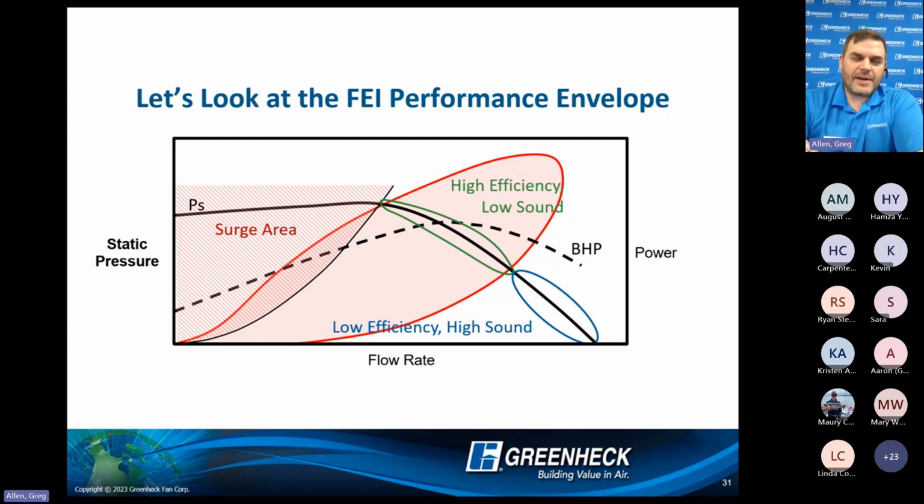Now, let's stretch just a little bit further. When you do employ technologies that give you variable speed, whether it's a VFD, an EC motor, or even a belt drive fan where I could adjust sheaves and pulleys, I have the ability to offset that fan curve in different directions, as we looked at with the fan RPM curve.